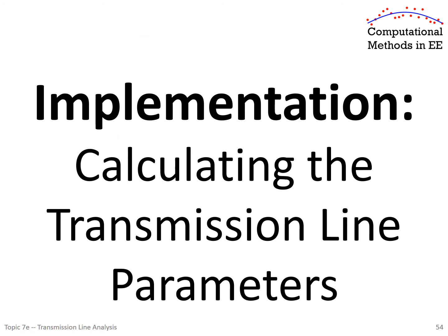Okay, so we derived our equations. We went to matrix form. We solved our matrix equations, and we got the electric fields: electric field E, electric flux density D, and scalar potential. From these, we want to calculate the transmission line parameters. We're now post-processing. The real simulation's done. We're just analyzing the results to get our meaningful parameters.